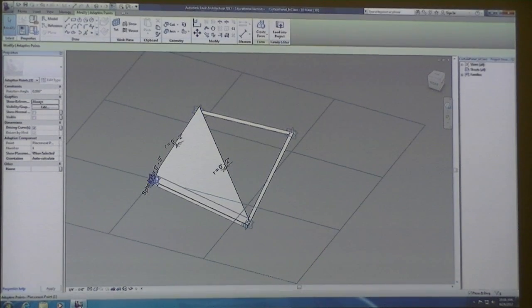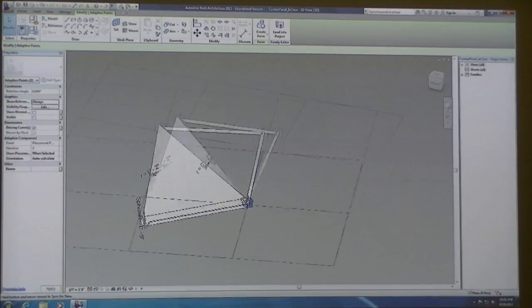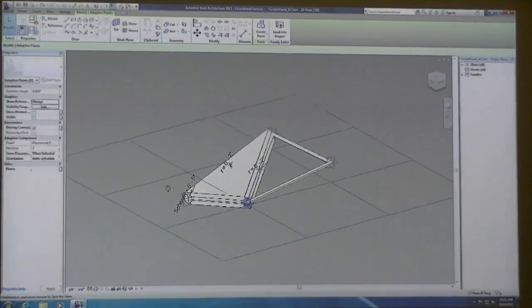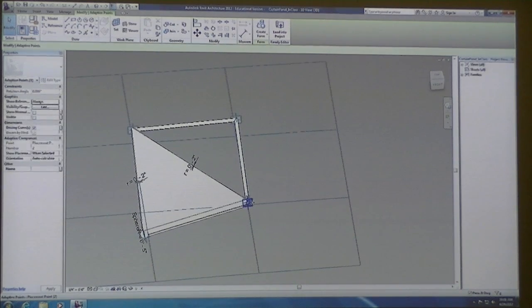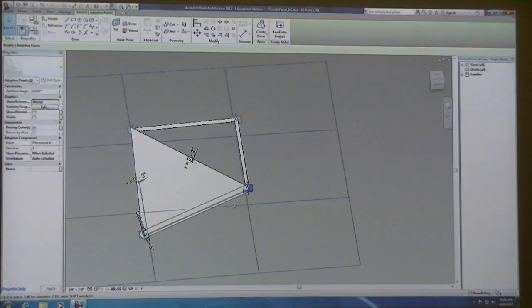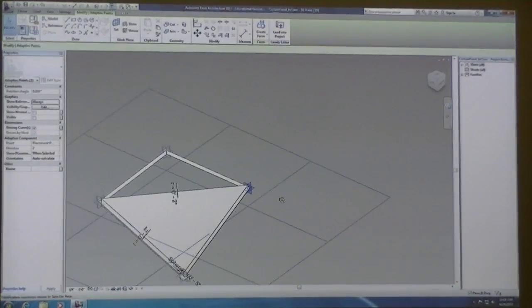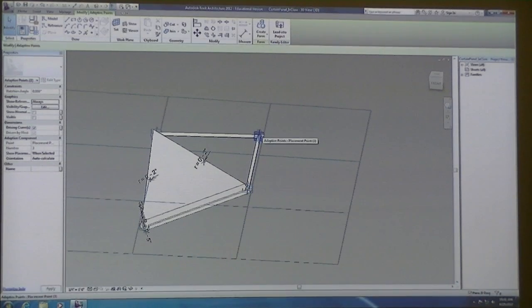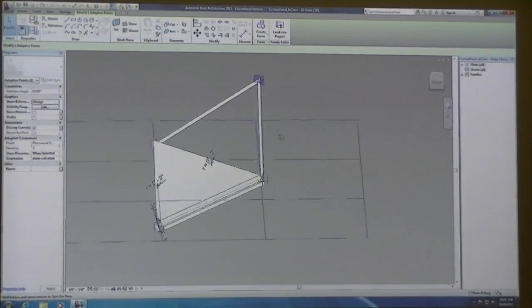If you've snapped correctly, this is a way to test your panel before you apply it somewhere. If you've snapped correctly to all the different points in the pieces, your whole entire form should move up and down and not become disconnected as you move these points away from the grid.